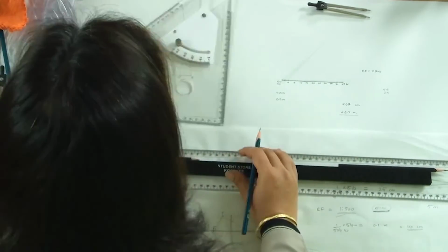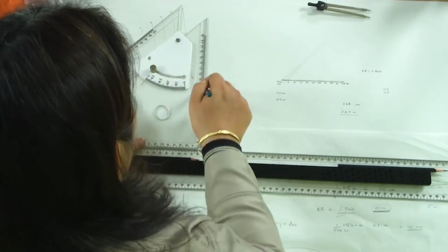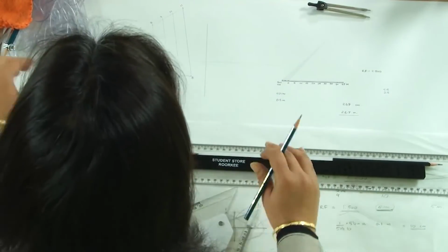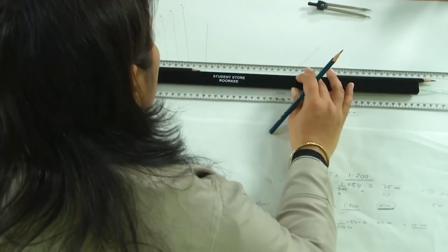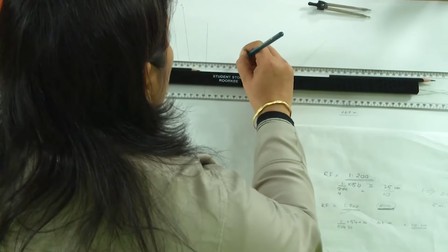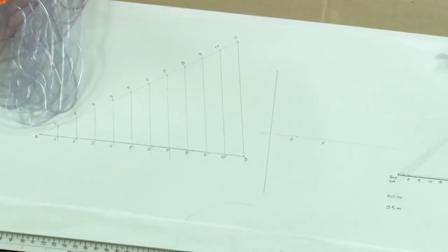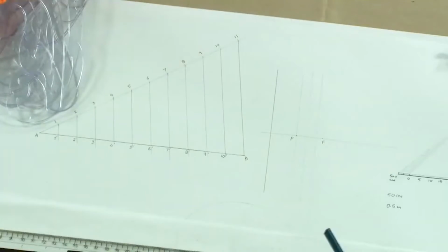So suppose we have a directrix given here. We will just draw a perpendicular axis for a given distance of focal point, say again 5 centimeters, what we had taken earlier, and the midpoint of that is going to be the point where the parabola will start or meet the axis. This is the focal point. Now what we'll draw here is, we'll draw these perpendiculars passing through these points.